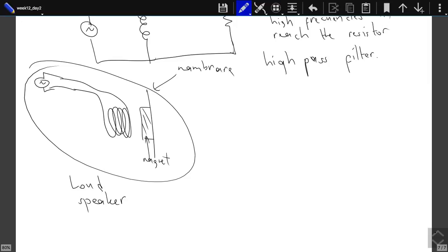How can a speaker produce multiple frequencies at the same time? Well, just send an electric signal that contains multiple frequencies. The superposition of two frequencies? Yeah. Is there a limit to the superposition, the number of frequencies that can be superposed? No, not really. Well, of course, there are limits, like a small loudspeaker cannot create very low frequencies. That is the limitation. With a very large speaker, it will be very hard to create high frequencies. There are practical limitations.